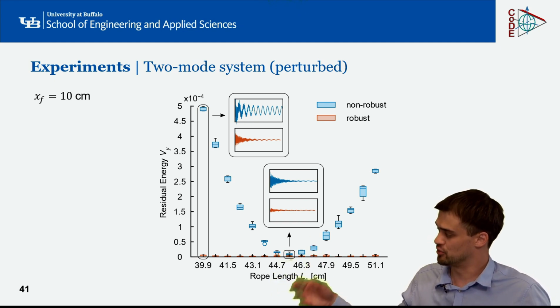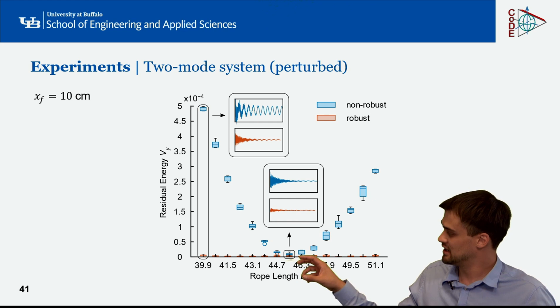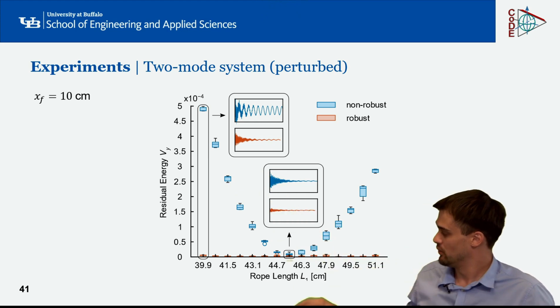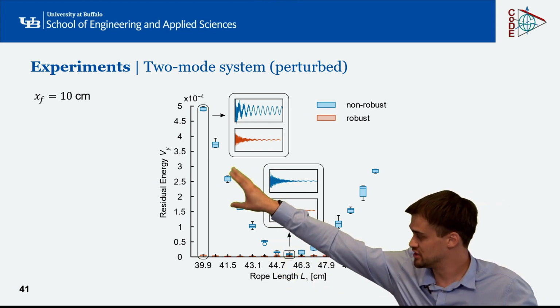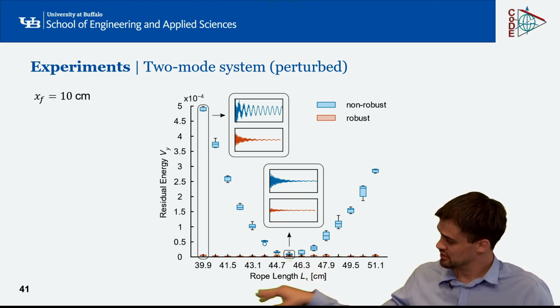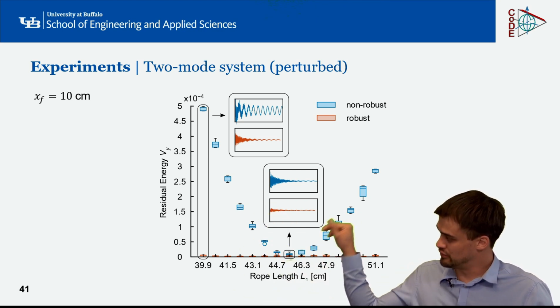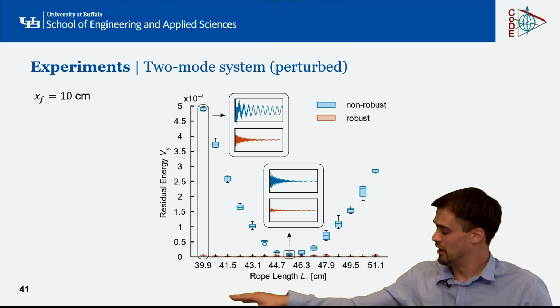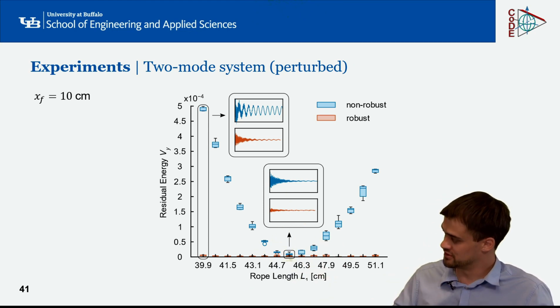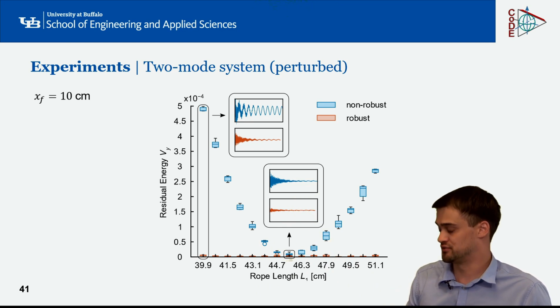And to make the figure a little bit more grasping for you, I plotted again the observations which we made from the swinging velocity in those 2 plots and in those 2 plots, where this is the unchanged rope length and this is a changed rope length. As we expect for a non-robust controller, the shape of the residual energy looks very sharp, almost like a wedge. However, the robust residual energy is staying flat when plotted in the same scale as the non-robust version.